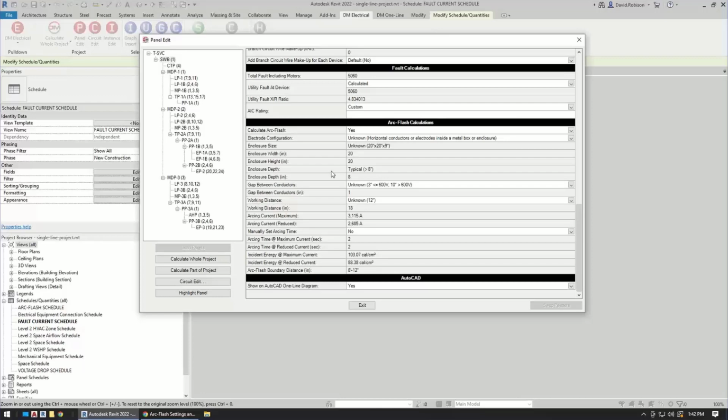I'm looking this up right now in my book, and I'm not seeing where the boundaries for the Lee method are. So with single phase, you start getting outside the range of what we even know in terms of arc flash. For single phase, you're usually looking at smaller voltages, where the assumption is you're not going to sustain an arc necessarily even there. So again, these are all based upon that IEEE standard.